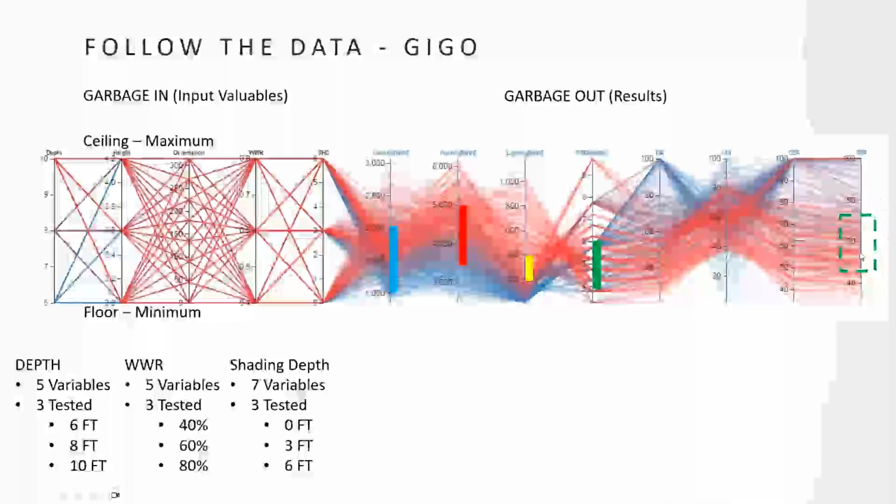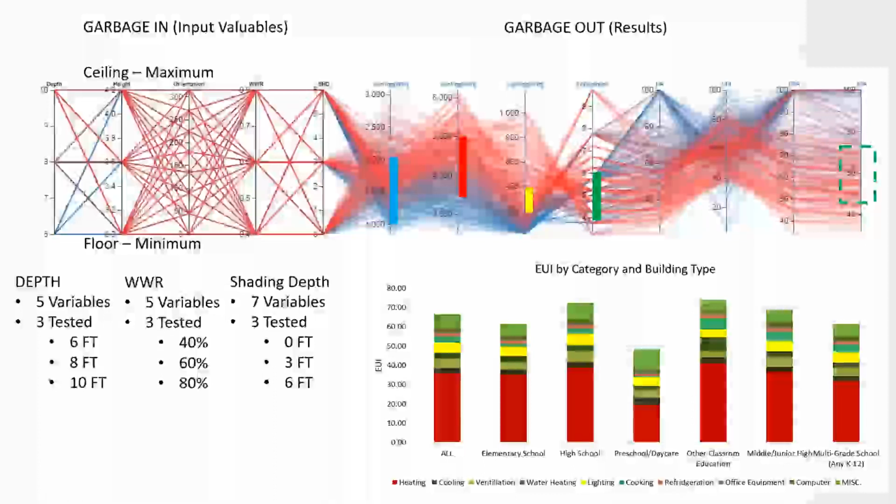And for some of them, you can make it theoretical. So this is SDA, Spatial Daylight Autonomy. This is used for LEED daylighting credits. And so here I drew the 45 to 75 for 4.1, which is the requirement for getting credit. So you have to be at least above this line. And if you're above this line, you'll get credit, but you just won't get any more. You'll get a nice pat on the back. Good job. That's about it. And you can do this earlier in the design process, not while you're in the middle of it.